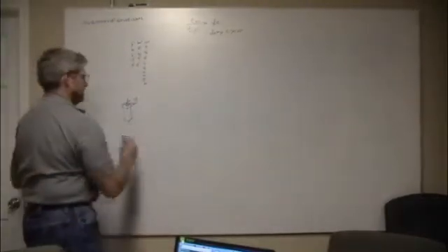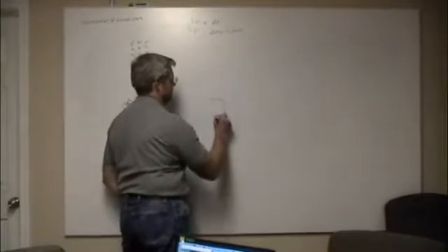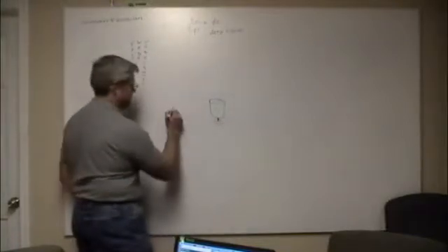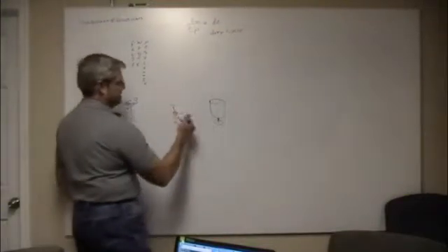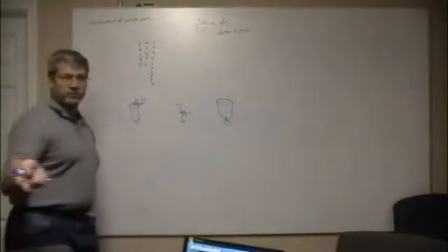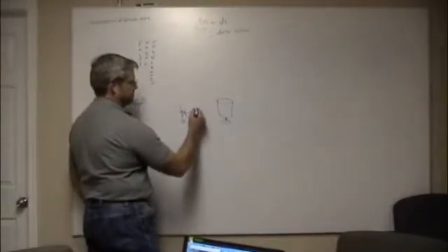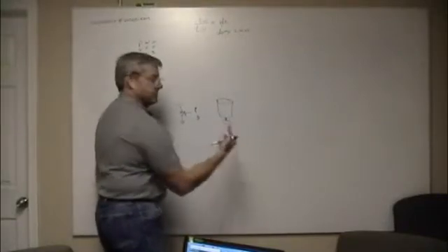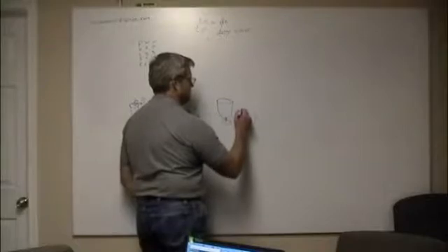So, take a DC motor, you hook its shaft to a potentiometer. As you turn the knob, it basically moves up or down the resistor. So this is a voltage divider. Remember we did voltage divider equations on like the first or second class. So the voltage changes. As you wipe it up, voltage goes up. As you wipe it down, voltage goes down. So as this thing turns that shaft, you know where it is. You get a specific voltage out. And then there's a little control circuit over here and an H-bridge.